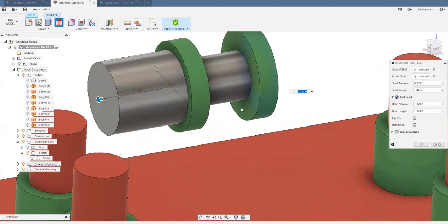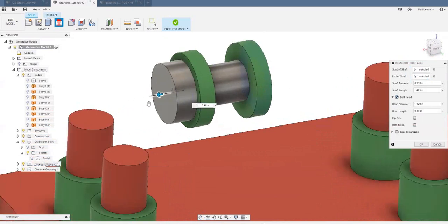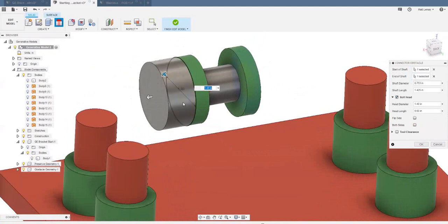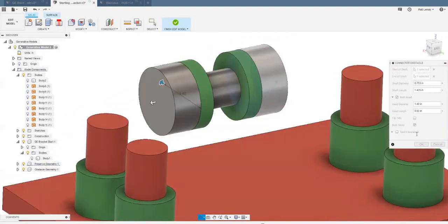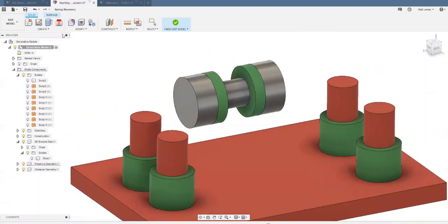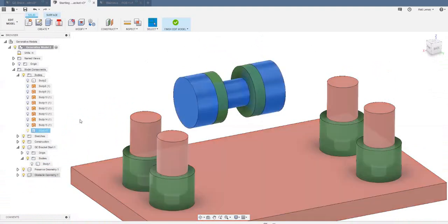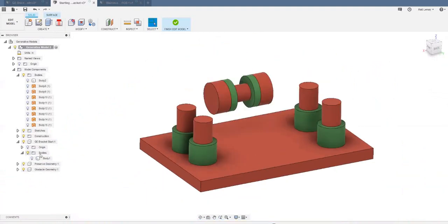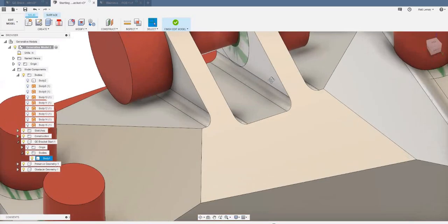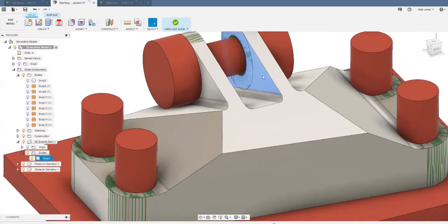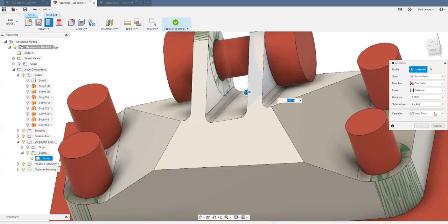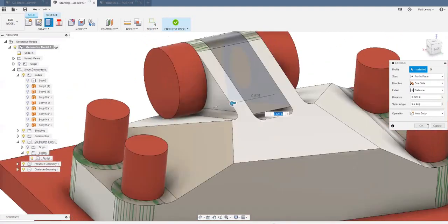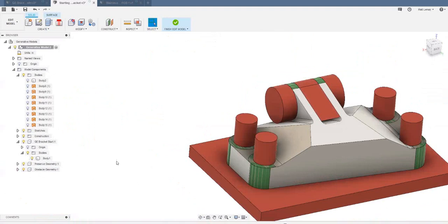And we can also set a clearance for the bolt head itself. So we can say we'd like to make sure we're clearing out geometry to actually apply the bolt to. And let's make sure to make that on either side. So you can see that was automatically created from that connector obstacle tool there. And then the same thing, I'll drag that new part that we created to our obstacle geometry folder. So the final thing that we would need to look at would be all of the geometry within this section here. So very similar to what we've been doing so far, I can just take one of the faces, extrude it to the other side, create a new solid for that, and then we can drag our solid to the obstacle geometry.